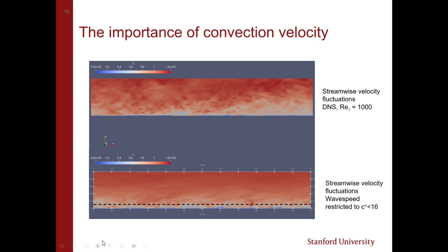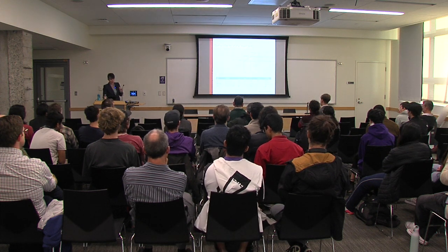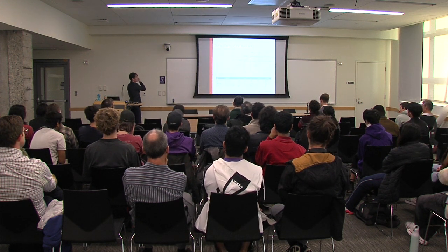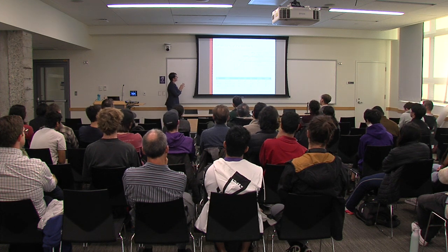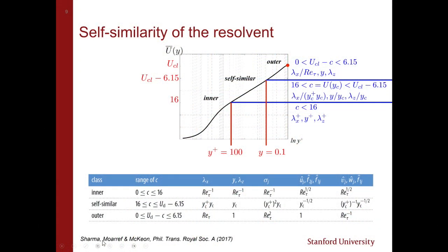So this picture, if I get time, I'll talk about a little later on, because this is our target now for a wall model for large eddy simulation, because we know a little bit more about this structure and how to model it. So space-time important. The other thing that's important, and the thing that I skipped over, is here. So the input to the resolvent analysis is the mean field. And for the channel flow, again, we already know a lot about this.